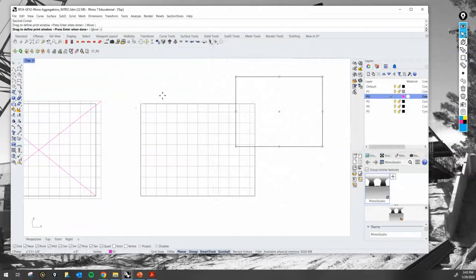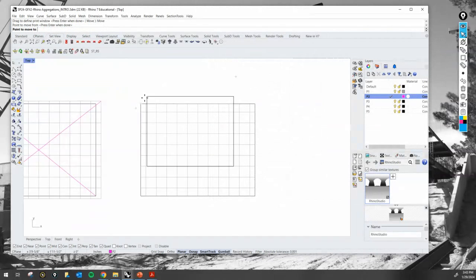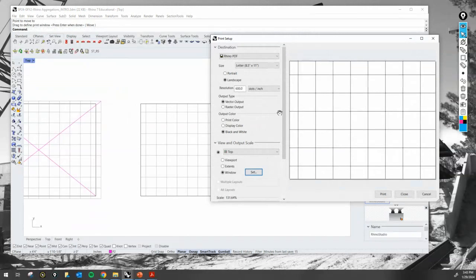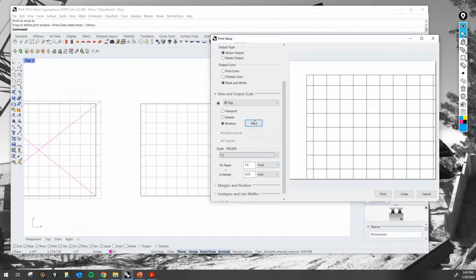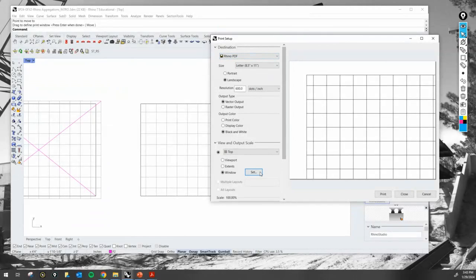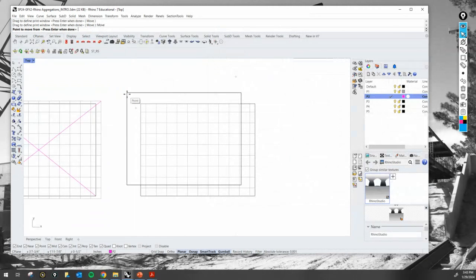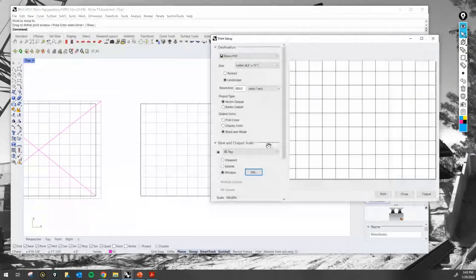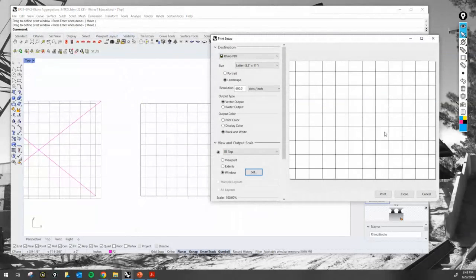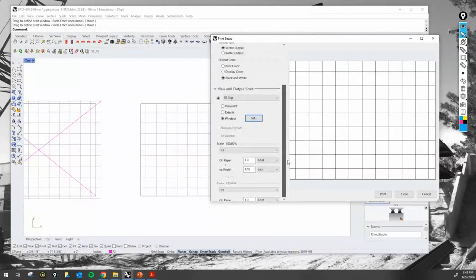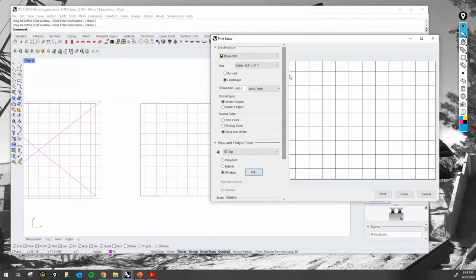All right, so I'm going to go one more time and set it, move from there to there. I've probably changed the scale, so I'll do a 1:1 right here, and I'll do a letter size. So set, move, from there to there, enter, and we have our sheet right here. Make sure that the scale is 1:1, which is 100%. That's also really important. It will become much more important. And then I can go ahead and print.